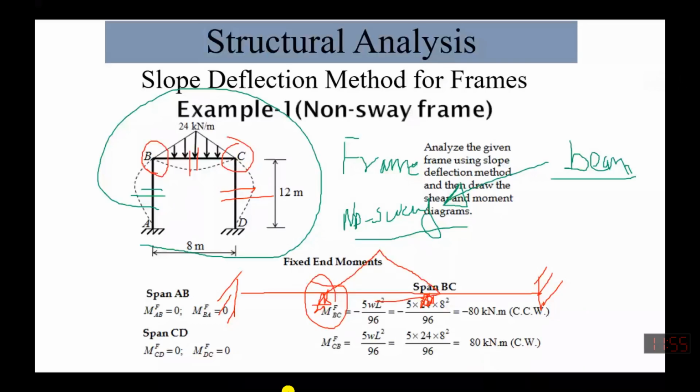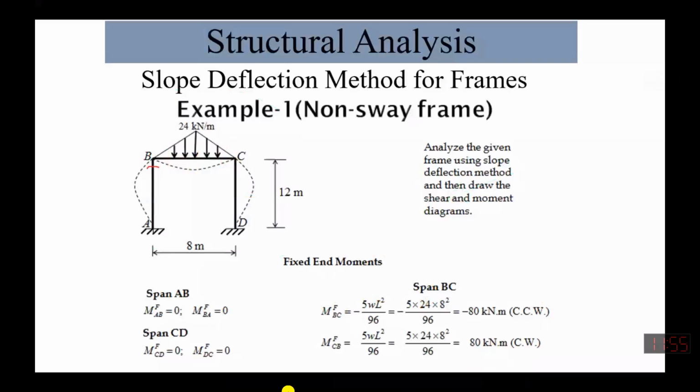Basically, it transfers the moments from one end to the other without losing its stiffness or integrity. This is the definition of a rigid connection. Let's say if it is 90 degrees, it will bend at 90 degrees. So this delta D is actually at 90 degrees. We are assuming that our material is not going under non-linear deformation.